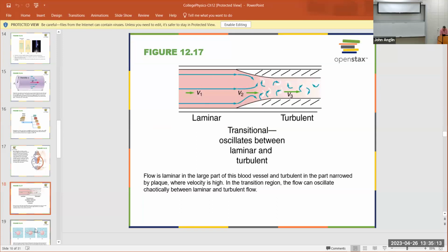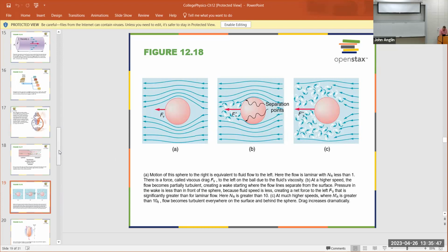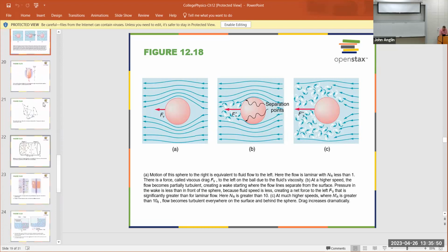So here's the transition boundary I was talking about. This has to do with aerodynamics. So you can see an example of laminar flow becoming turbulent flow. And in aviation and aerodynamics, this is drag. So you would like this, right? You would like for the flow to be laminar. This is bad because you're not getting that flow over the wing. And if you're not getting the flow over the wing, you're not creating the pressure differential and you're not creating lift. And the airplane falls out of the sky like a brick, which is sometimes desirable and kind of fun.